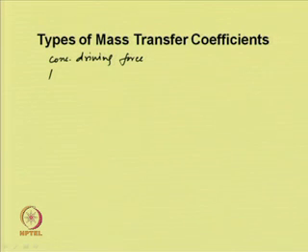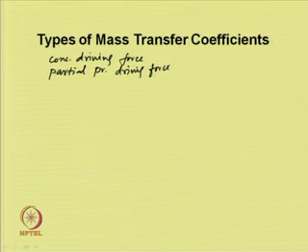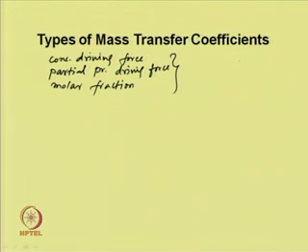We can use partial pressure if it is in the gas phase, partial pressure as the driving force, and we can also use the molar fraction as the driving force, and so on. But in case of heat transfer, only the temperature is the driving force. So, depending on the situation, we can define the mass transfer coefficient.